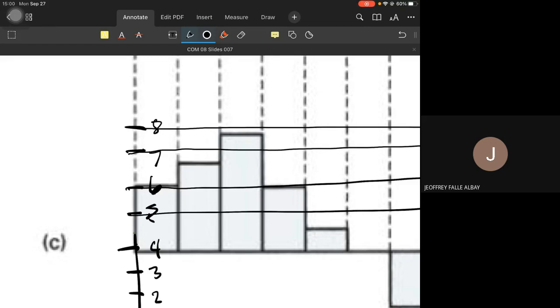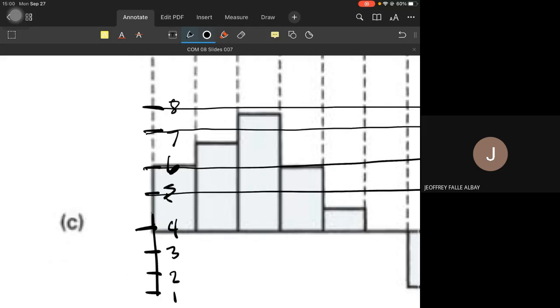And each of these levels is then assigned a binary code. So the output now is already our PCM code. And this is just for example purposes. Let's say level 8 is assigned 111. Level 7 is 110. Level 6 is 101. Level 5 is 100.